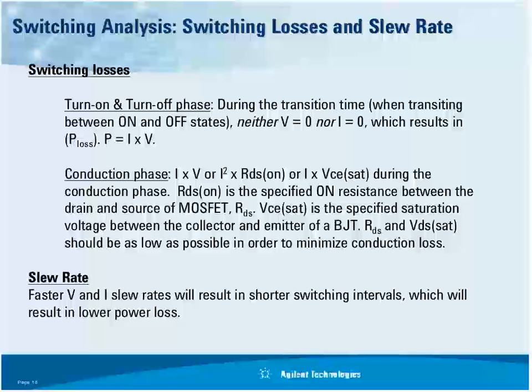Now let's get into the switching analysis, which many consider the more important measurement to improve efficiency. As I mentioned earlier, there are several important phases of switching analysis. There's the turn on and turn off phase, and that's where the transistor is going through the linear range. And then there is a conduction phase, where the transistor is conducting, there is a small amount of voltage across the transistor, and there are losses during the conduction phase.